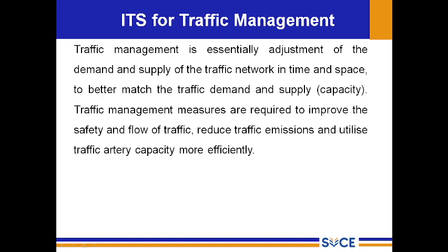ITS for traffic management. Traffic management is essentially adjustment of the demand and supply of the traffic network in time and space to better match the traffic demand and supply, that is capacity. So what they are saying is, the demand is the vehicles actually going. You can count the number of vehicles per hour. Similarly, supply, the capacity, is also measured in vehicles per hour. Depending upon the lane configuration, width of lanes or number of lanes, the capacity is going to change.